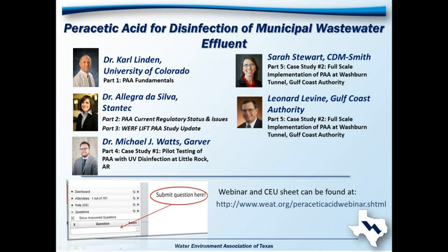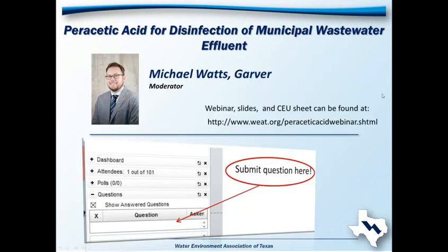Sure, thanks for the question. Yes, it's very similar to chlorine. You can use both the DPD wet chemistry kits where you take a grab sample and there's ampules and it's a colorimetric test, or you can also use amperometric probes and even DPD-based probes that are inline probes to have real-time monitoring.